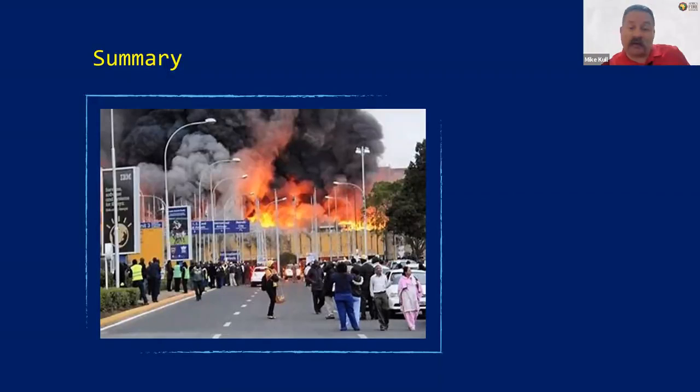Now, maybe that picture in our mind may change when we get on the scene, and that's where we're going to do our first 360, our first complete walk around of the incident scene. We're going to walk looking at it from every angle, from every direction of the compass. That's why we call it that 360, to get the complete picture of what's going on within the building. As we're doing that, we're looking at building construction, flow paths, smoke, the flames, all sorts of things that we talked about earlier.